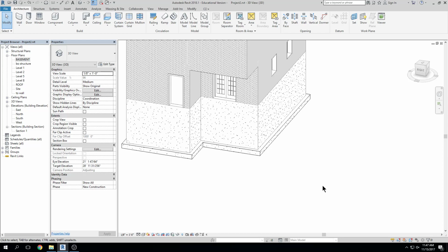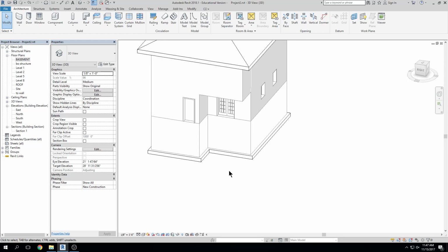You could use SE wall as your layers, but then it could be confused with, like, hey, who drew these? Well, it says SE wall. Well, that's a structural engineering layer. Yeah, but I drew it on that. Well, why did you draw it on that? Well, because I wanted to. Well, it's not right, you know? It's kind of that same conversation. And the structural engineer would take responsibility for those items, right? And then the second reason I don't use that is because it's just not as easy to alter them, right? But it's fine. I mean, if you want to go that way.